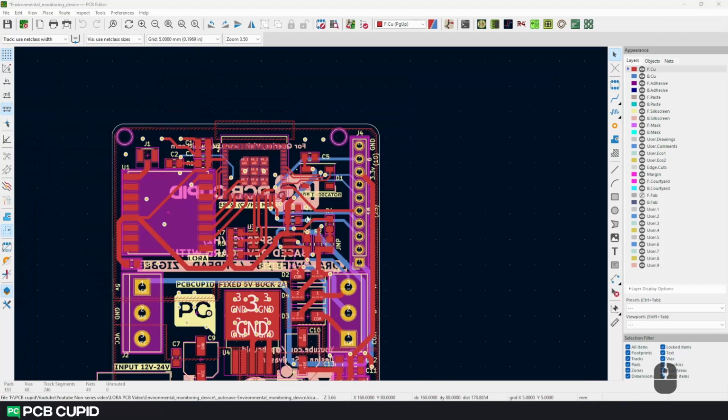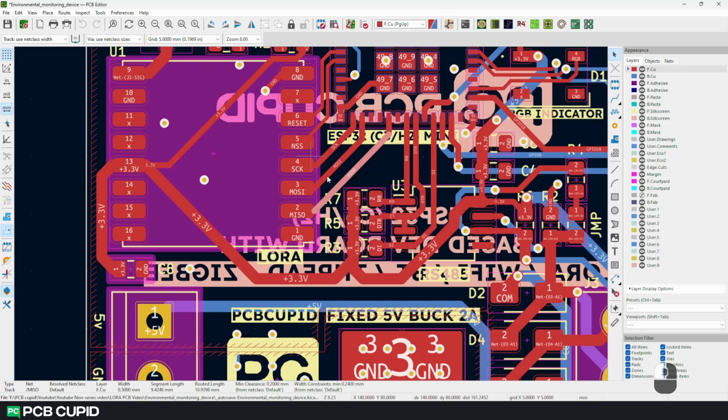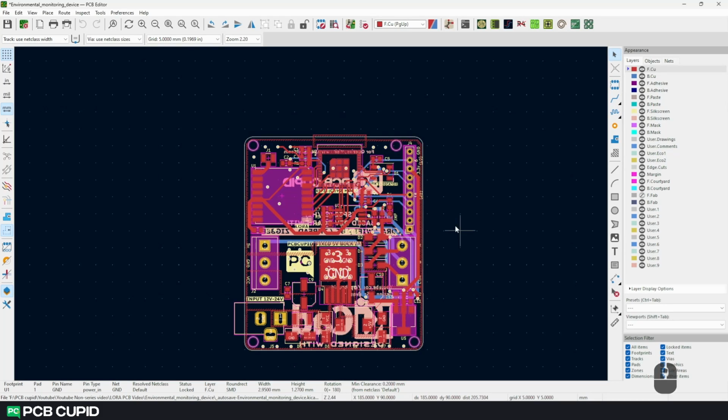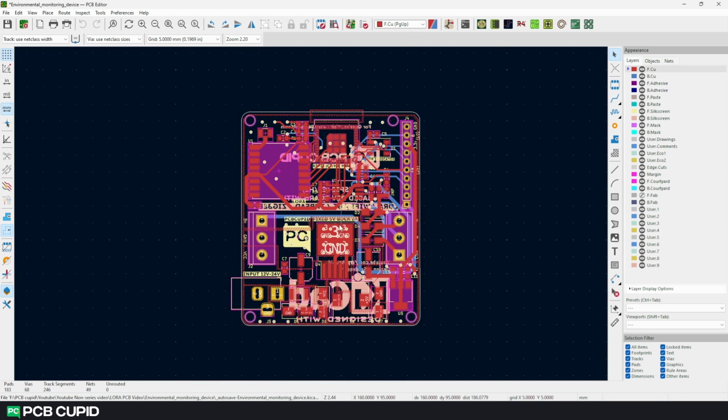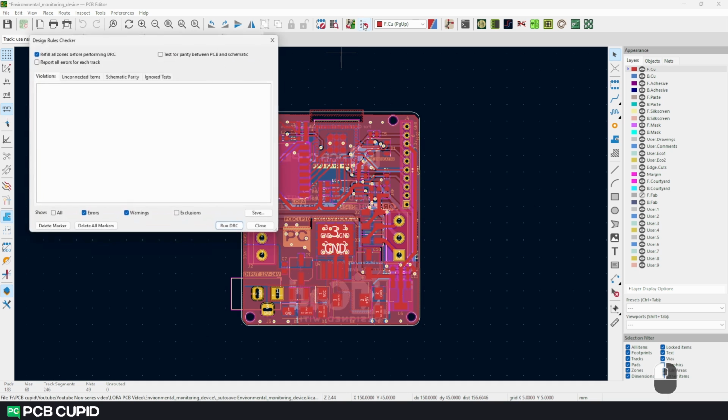Making sure to take my time to efficiently route the PCB and also considering the clearance between the traces, between the trace and edge cut, and between the trace and solder pads. To keep the PCB layouts organized and efficient, I'm always trying to refer back and forth between the PCB layouts provided in the datasheet or the application notes.